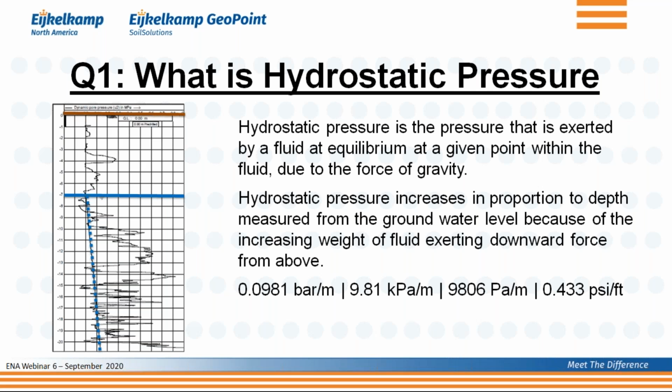So generally speaking, what I suggest is, if they don't know the hydrostatic pressure, because in order to analyze your CPT data, as I showed you earlier, you need that water table, do your CPT. When you see a friction ratio that is 1% or less, then you know that you're in sand. Then pick a level there where you think you are below the water table, and just do the dissipation test, and that way you can determine how much higher above where you are at that time the water table is. Any other questions?